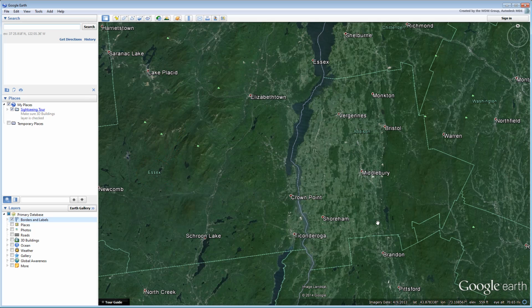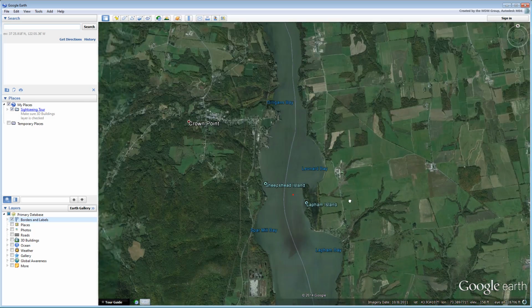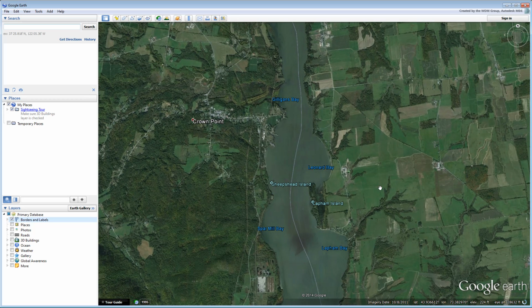You're almost ready to fetch GIS data that will help you build a 3D surface of the needed terrain in Civil 3D. Before you do that, you need to consider that you will also need a satellite or aerial image to eventually use as a texture in 3ds Max. 3ds Max and 3ds Max Design do not incorporate aerial imagery, so you need to manually create a terrain texture to drape over the 3D surface. Often, this is the kind of work a civil engineer would contract out to professional companies. However, the next movie shows you how you can create your own ground texture using Google Earth and other similar tools.